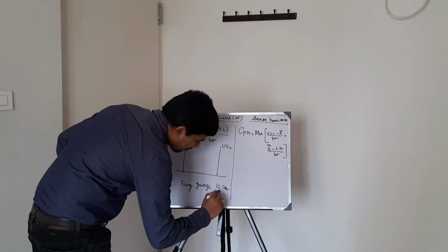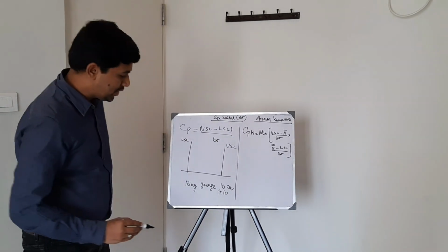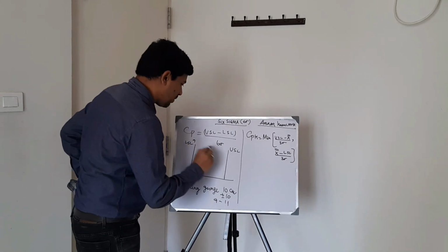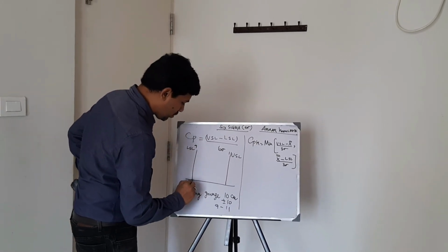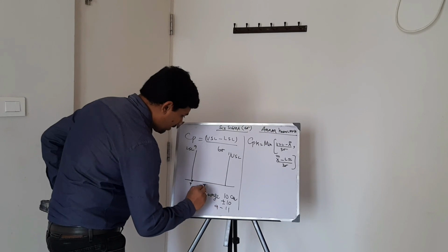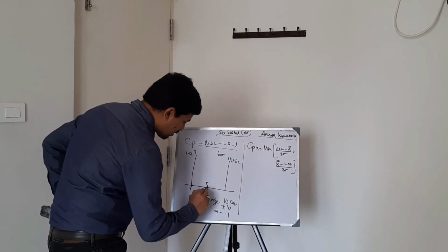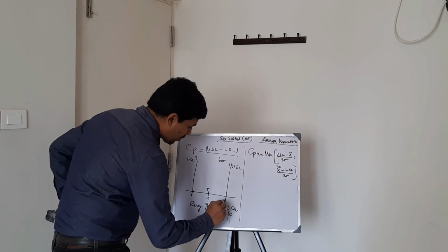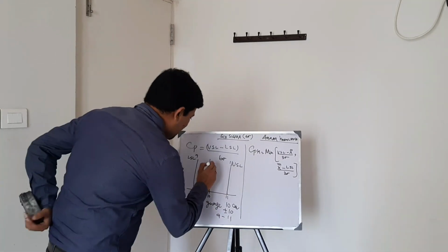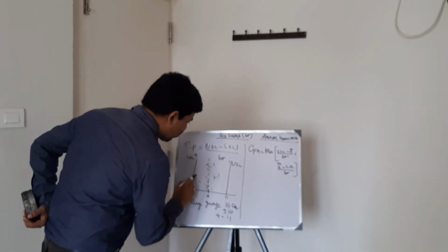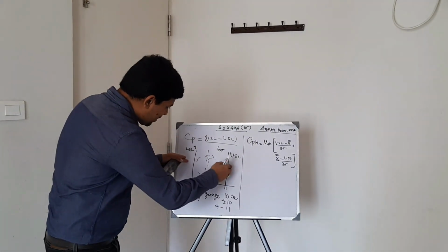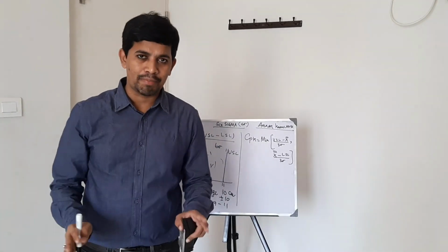It has a tolerance of 1. That means you can flip the range between 9 and 11. So this is your LSL and USL. You can put 9, and the actual specification target line is 10, and then the USL is 11. All of these values, if they fall here, you're comparing only with the customer specifications. Anything within this range, the parts are acceptable.